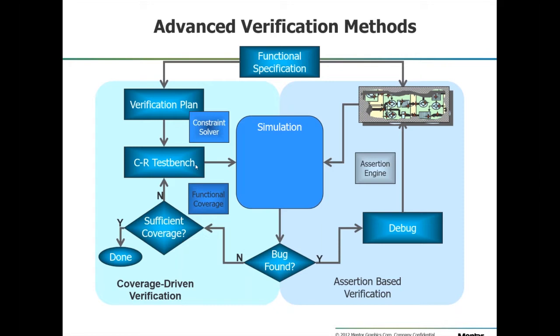So that is this idea of sending randomized data. But we can't just totally randomize, because it'll take forever to get my functional coverage up to 100% to say I'm done. So that's where I have constraints on my randomization. I can say my packets have a variable length, and maybe 10% of them should be short, 0 to 64 payload, and then medium maybe 40%, and large 60% something. So you put these constraints on there.